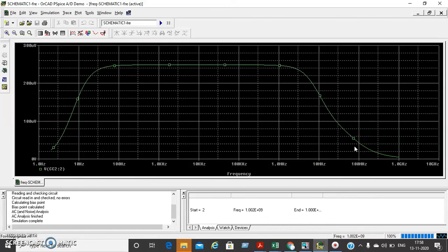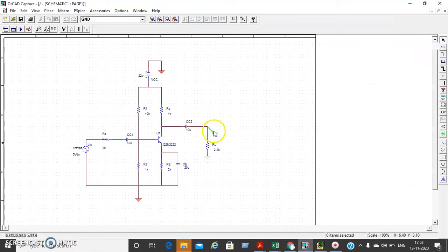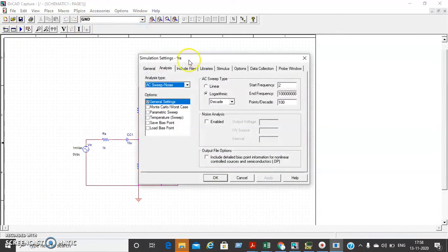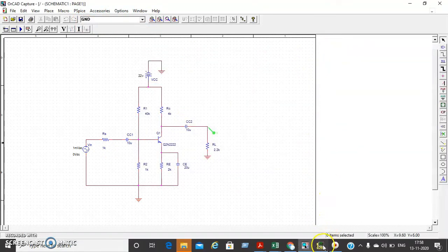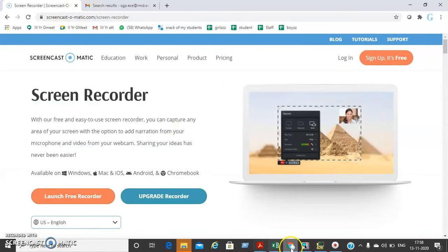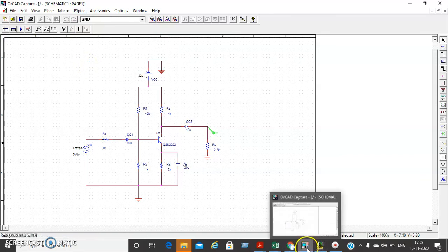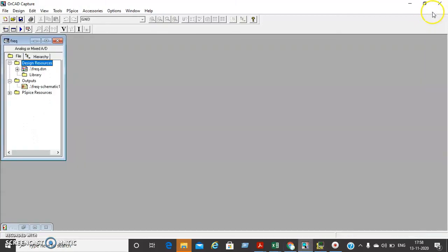Is it clear? Yeah, so for your experiment's sake, we have to take a screenshot of this particular diagram, and then we have to take the simulation profile. Next you have to show the output figure window, and finally you have to show me the netlist, PSPICE view netlist. Yeah, it will be opened in your session log, I think so. Let me minimize this.